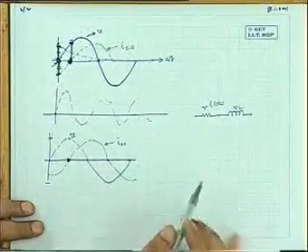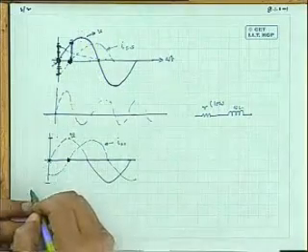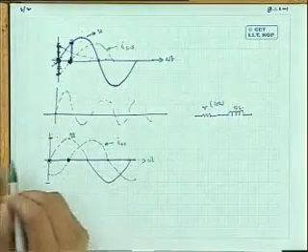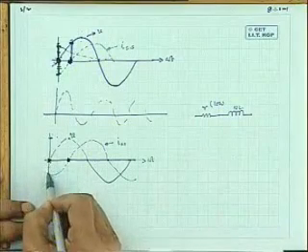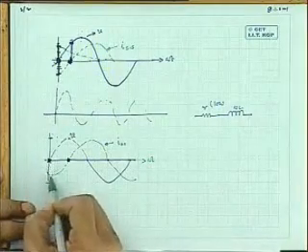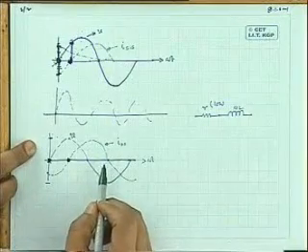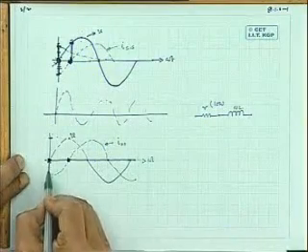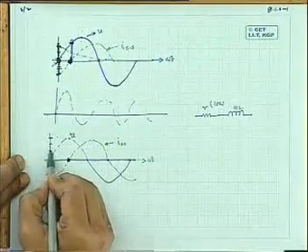But the situation will be somewhat different if the circuit is closed at this point. This is the time axis, omega t. If you close the circuit at this point, omega t equal to 0, how much is the steady state current? Negative this much. Do you think only this current can exist in the circuit at that point of time? No, because inductor current cannot change instantaneously. So there has to appear a current whose length will be equal to this, which you cut down here.